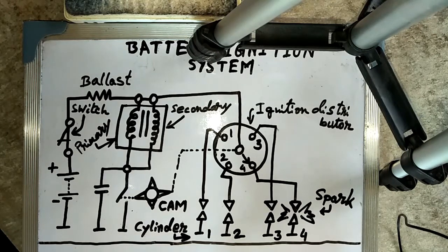Such current charges the condenser to a voltage much higher than the battery's voltage. The condenser then discharges into the battery, reversing the direction of both the primary current and the magnetic field. The rapid collapse and the reversal of the magnetic field in the core induces a very high voltage in the secondary winding of the ignition coil.